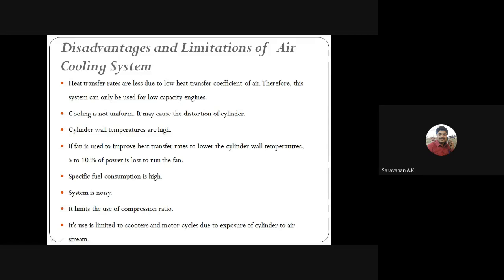It is limited to low speed and medium speed engines, especially scooters and motorcycles, due to the exposure of the cylinder in the airstream. These are all the disadvantages and limitations of the air cooling system. It is called the direct cooling system, or the air cooling system.